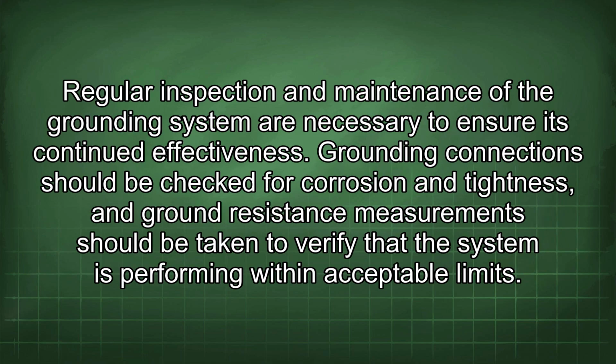Regular inspection and maintenance of the grounding system are necessary to ensure its continued effectiveness. Grounding connections should be checked for corrosion and tightness, and ground resistance measurements should be taken to verify that the system is performing within acceptable limits.